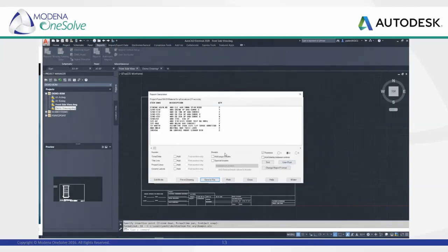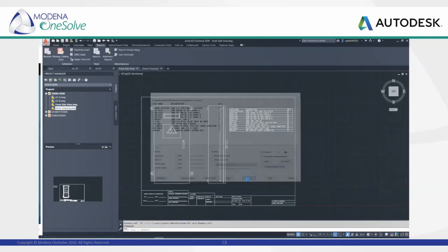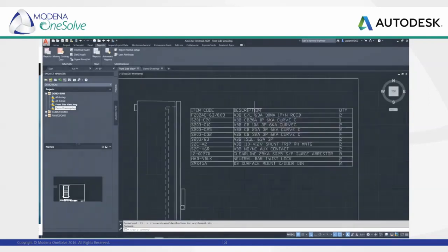So what I'm going to do is quickly save this Excel spreadsheet in my BOM ERP folder, and that concludes the demonstration on how to leverage AutoCAD Electrical in control panel design to quickly generate a bill of materials list that can be plugged into your ERP system. Just to have a look quickly, before we shut down, let's have a look at the bill of materials lists that have been populated.